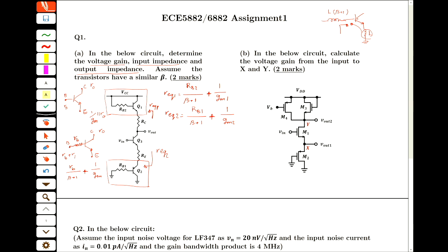The same. And then we can replace this one with this R equal 1, the upper network, and the lower network with R equal 2. So the impedance that we have in the collector is RC plus R equal 1, and the impedance in the emitter is RE plus R equal 2.